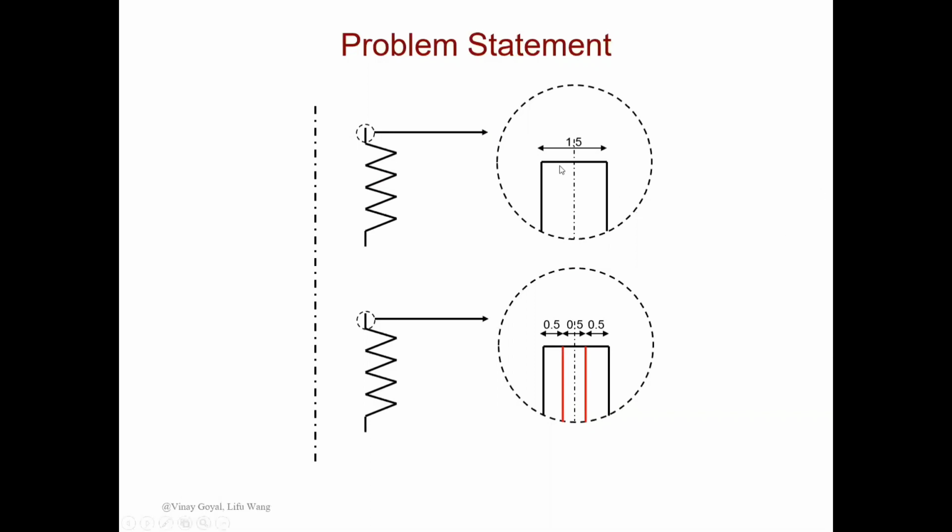And the way we draw it is first we create a central line for both models. These central lines are exactly the same as our previous simulation, with the inner rotation diameter 50 millimeter and the outer diameter of 100 millimeter. And from this central line, we make the boundary for our shell element. And let's see the final element GUI settings.